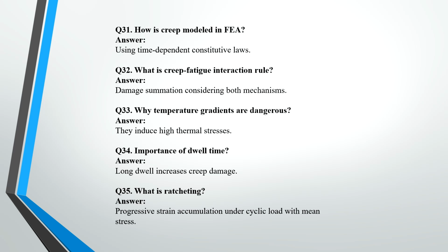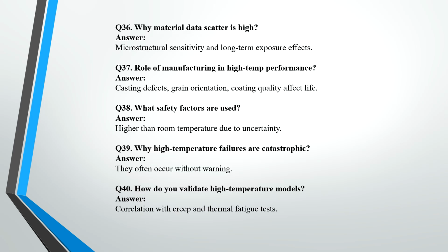Why are temperature gradients dangerous? They produce high thermal stresses. Importance of dwell time: long dwell increases the creep damage. What is ratcheting? It's a progressive strain accumulation under cyclic loading with mean stress.